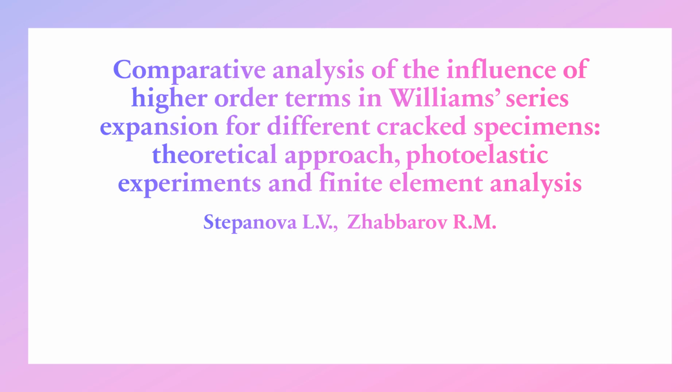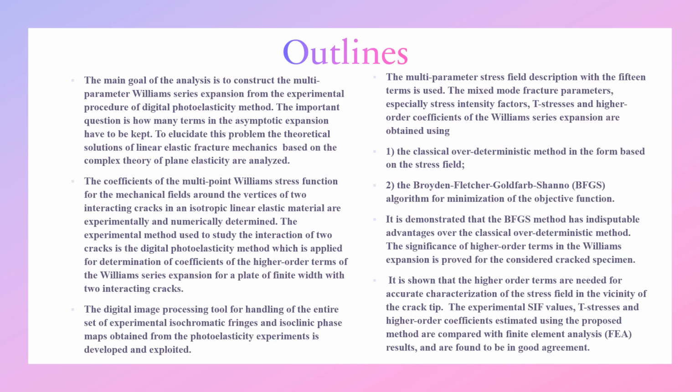Let me present our research, a comparative analysis on the influence of high-order terms in Williams series expansion for different cracked specimens: theoretical approach, photoelastic experiments, and finite element analysis. The main goal of the analysis is to construct the multi-parameter Williams series expansion from the experimental procedure of the digital photoelasticity method. The important question is, how many terms in the asymptotic expansion have to be kept?